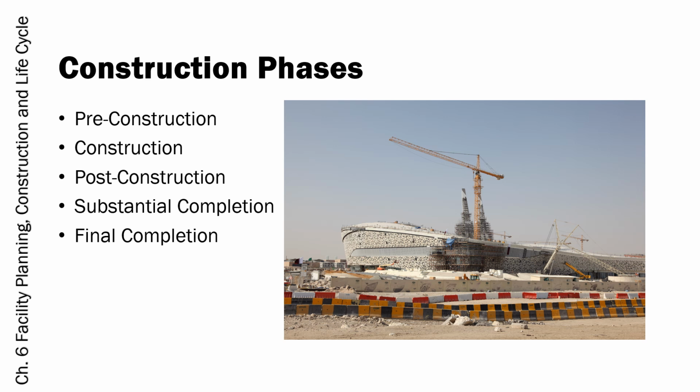There is the substantial completion phase, which is a milestone that's reached when the project is practically complete, meaning that the building is ready for its intended use, even though some minor work may still remain. At this point, the building is safe for occupancy and the owner can take possession. The contractor typically submits a certificate of substantial completion to indicate that the work is almost complete, and final inspection may still be pending for some areas.